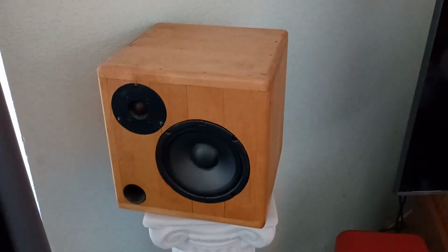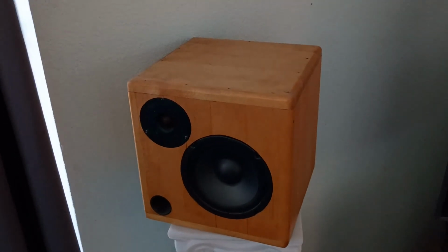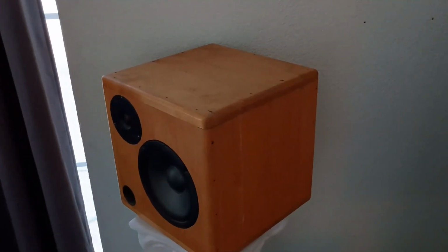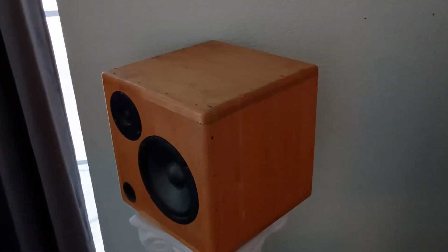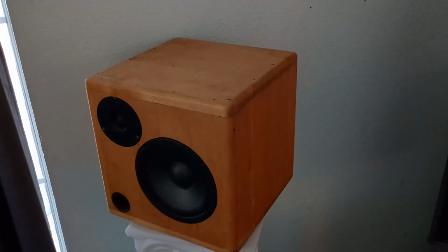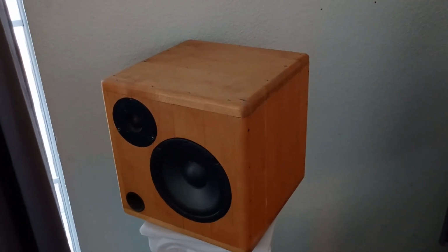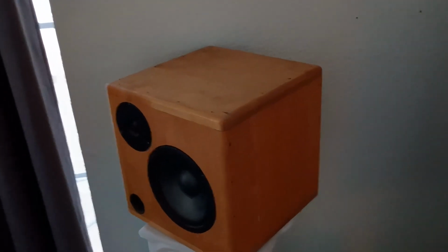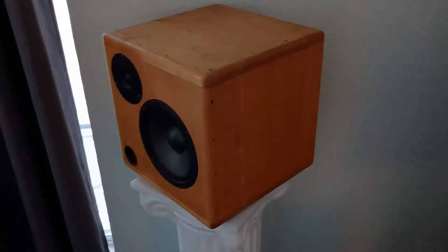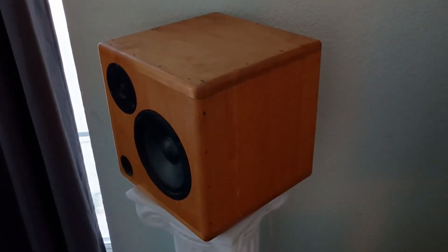And I kind of patterned these after a company that was making speakers in Ohio at the time called Design Acoustics. I don't even know if they're in business, but they used to build a speaker that looked very much like this. And actually, you're not supposed to build speakers in a cube, because when you build them in a cube, it creates reflections inside the enclosure that are hard to damp out. But what I ended up doing was I used rock maple to build the enclosure, and then I stuffed it with fiberglass, and they actually work very, very well.